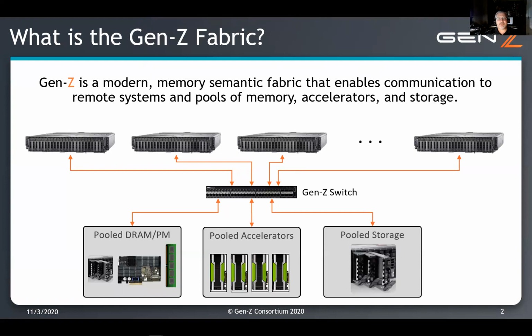And those endpoint devices are going to be in pools. They're going to be in memory or persistent memory. They're going to be accelerators. They're going to be NVMe drives. And what Gen Z brings is true high performance because it's got very high bandwidth as well as low latency. It's got a scalable architecture. It's also highly reliable. It allows for multiple links and built-in retries. And then it has hardware enforced security. And it also drops into your environment without requiring code changes.